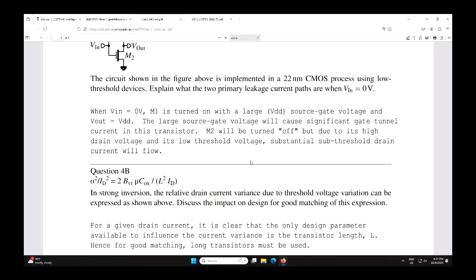If you have a transistor that is given, as made for you, something you take from a lab drawer, then in that case you wouldn't have anything to play with. The only thing you could do is increase the drain current. Now, increasing the drain current, if you look at the other equation, for given dimensions would increase the effective voltage, which makes the threshold voltage less important. So that's why it gets better matching like that.